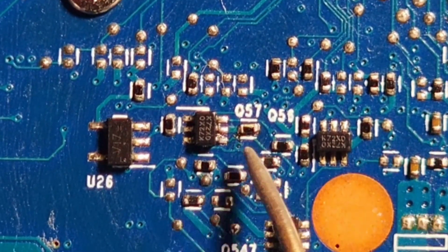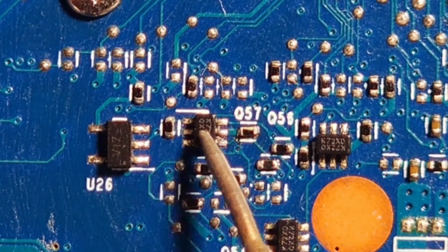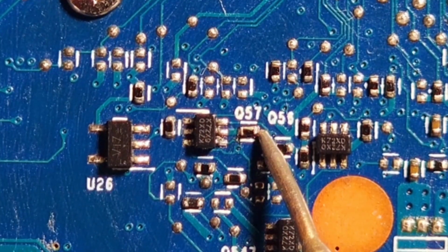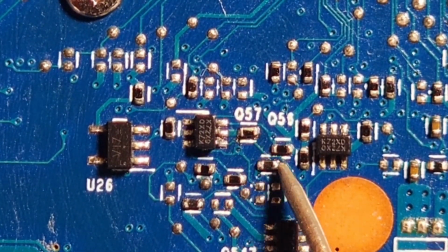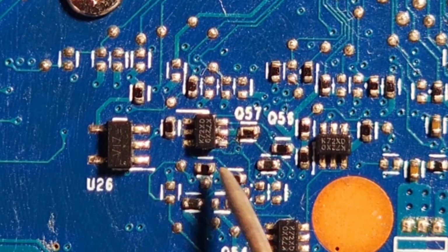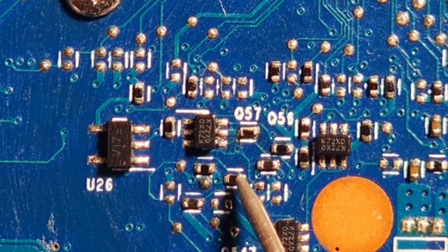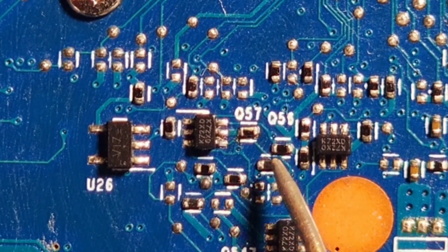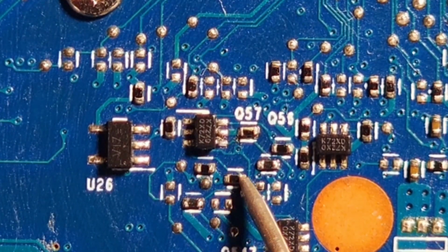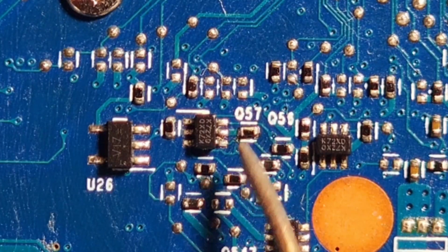Okay, so here we found the Q57 IC in this place, and we have the resistor here. This is the pull-up resistor that gives 3.3 volt supply into this data line, and there is another resistor, I think this one or this one, which supplies the same 3.3 volt run power supply into this data line. This data line comes to this chip and goes out of this chip through this line here. So we are going to check these two resistors to see whether their resistance is appropriate.